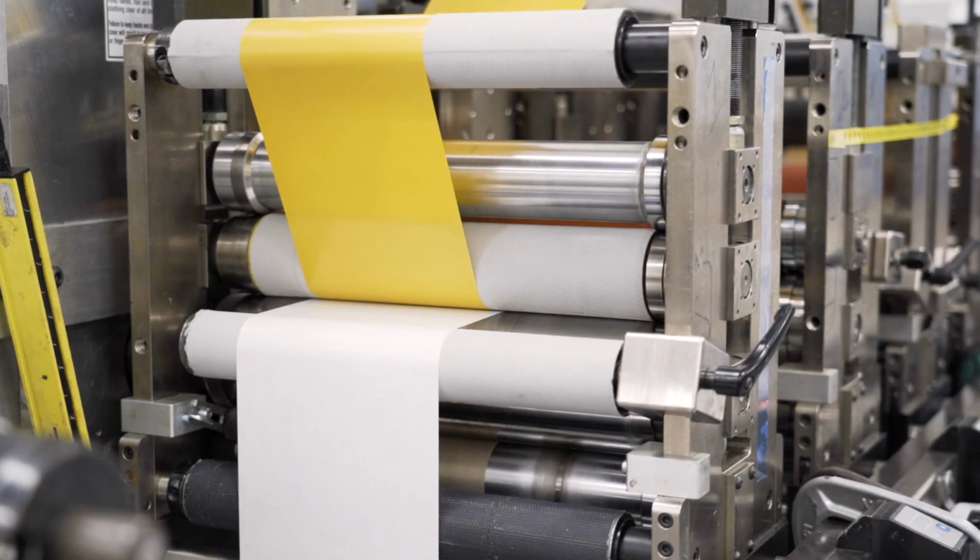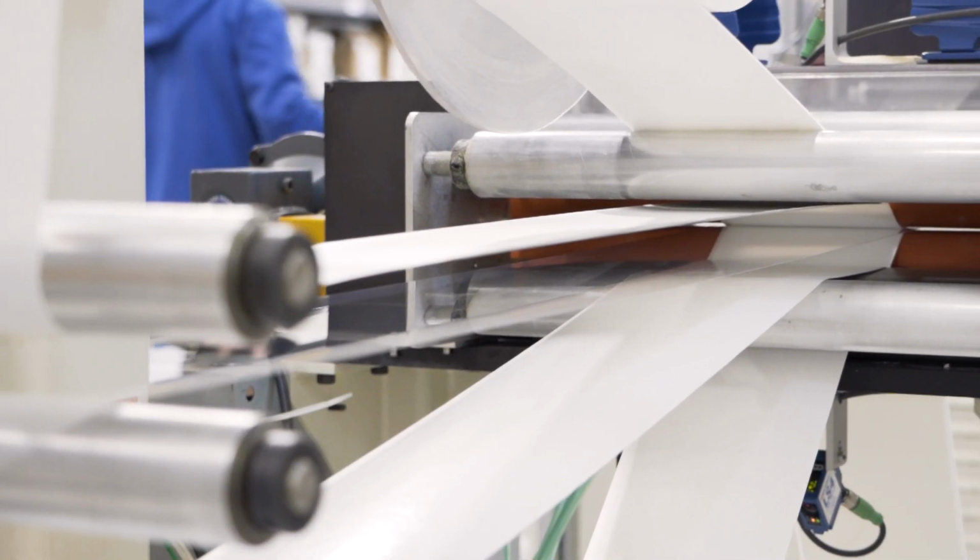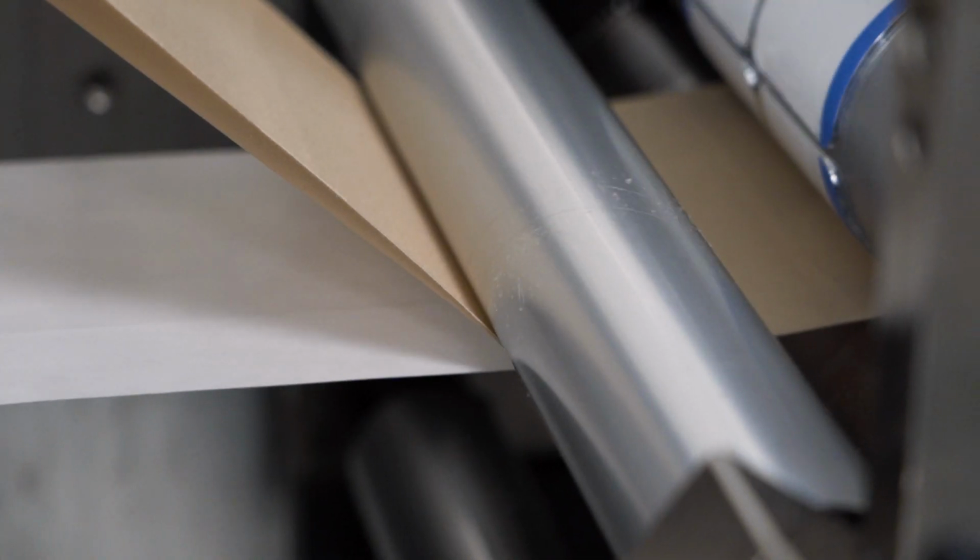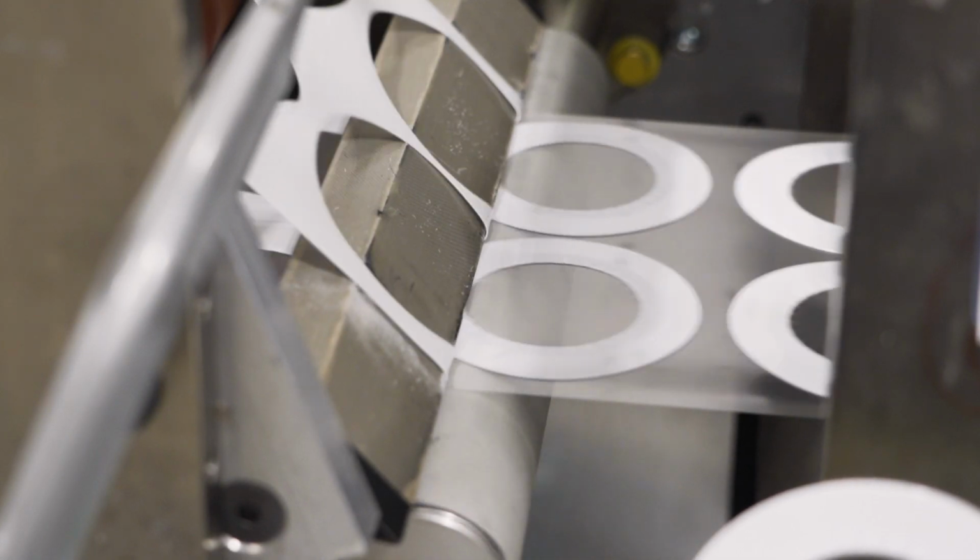The third major issue comes down to liner thickness, which plays a surprising role in both material handling and structural stability. A liner that is too thin might lack the stiffness needed to support the adhesive and part shape. As a result, parts might crumple and deform, making them more difficult to work with and potentially affecting their final performance. A thicker liner can offer the support needed for precise handling. However, excessive liner thickness may create issues as well as add an increased material cost.